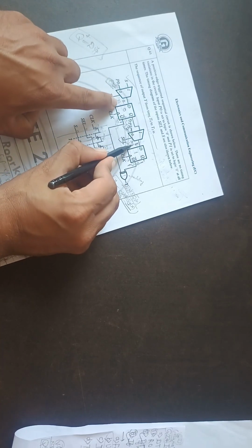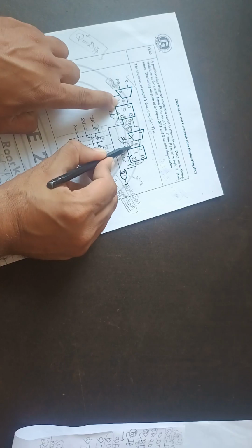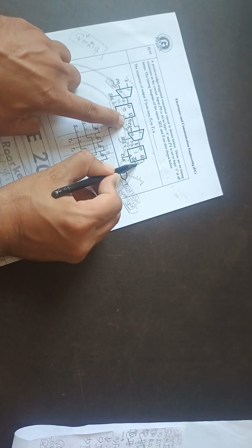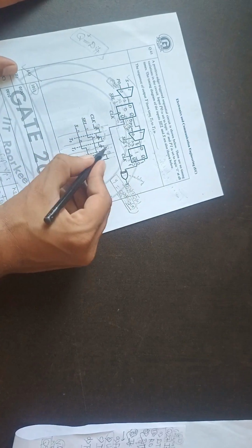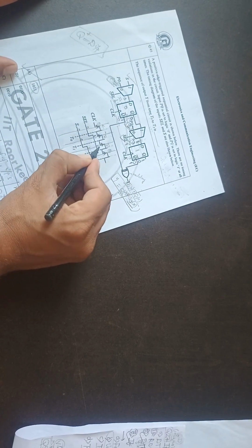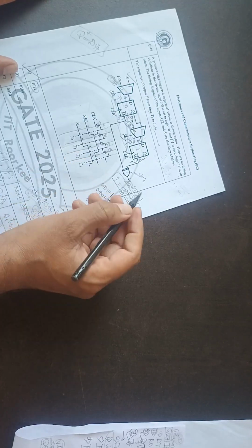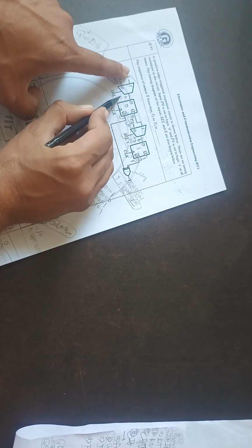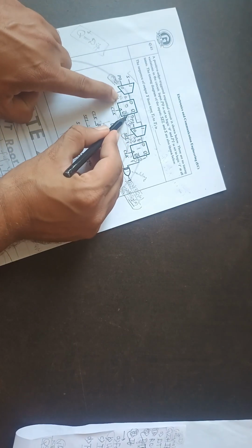So just before the second clock edge the input was 0 0, so after the second clock edge the output will be 0 0. Okay, so this is the situation after the second clock. Then just before the third clock edge, this is 1, this is 1. Both select and S are 1, so this select is 1 and this 1 will come here. The select is 1, so this previous bit will come.